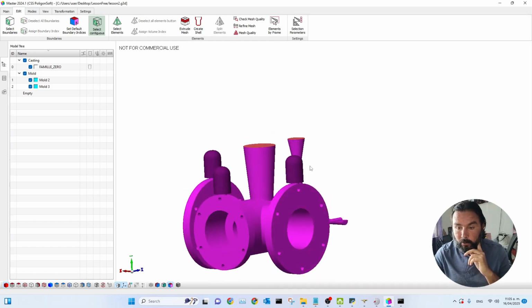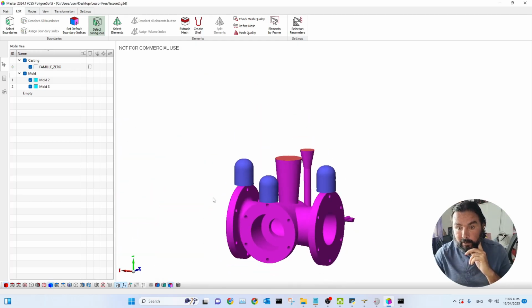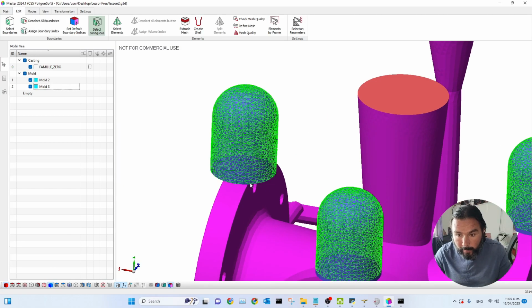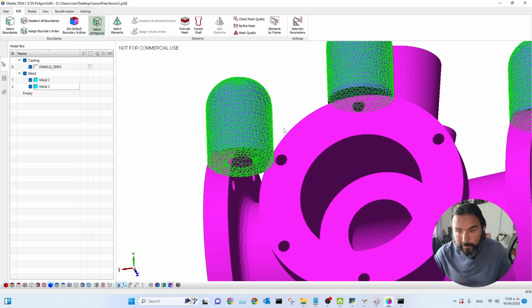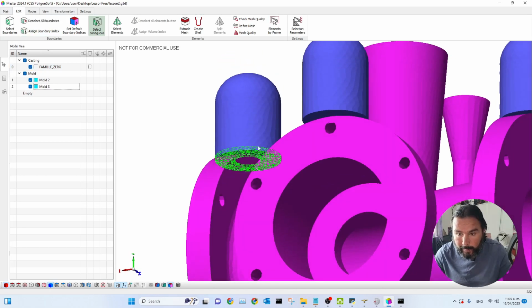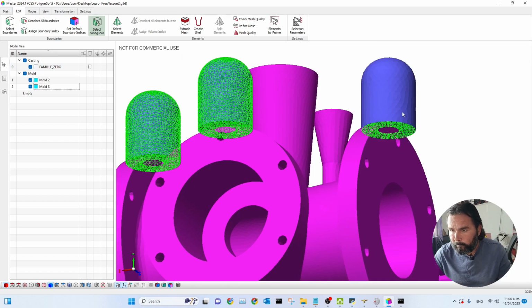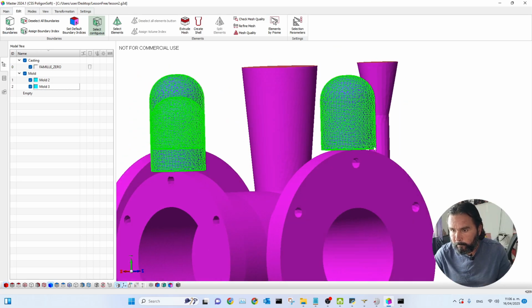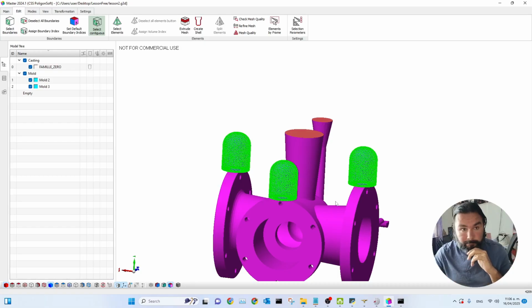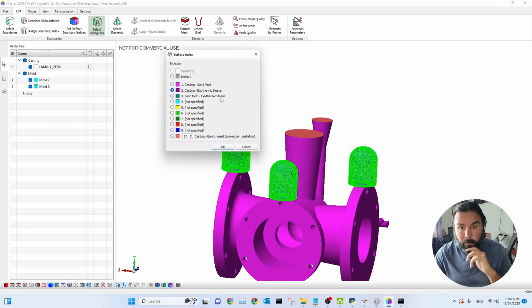We can now see that the color of this boundary changed here. We also have to do it on the outside to establish the heat exchange parameters between the external part. It seems I selected something extra, but it's not visible. To establish the heat exchange between the external part and our mold, here we assign the index corresponding to the heat exchange between the sleeve and the mold.